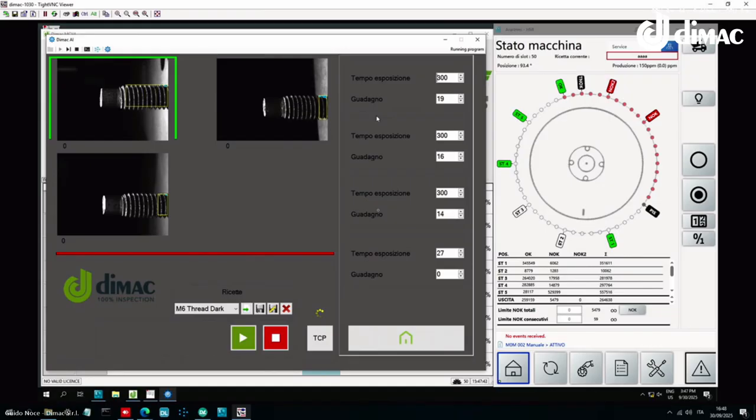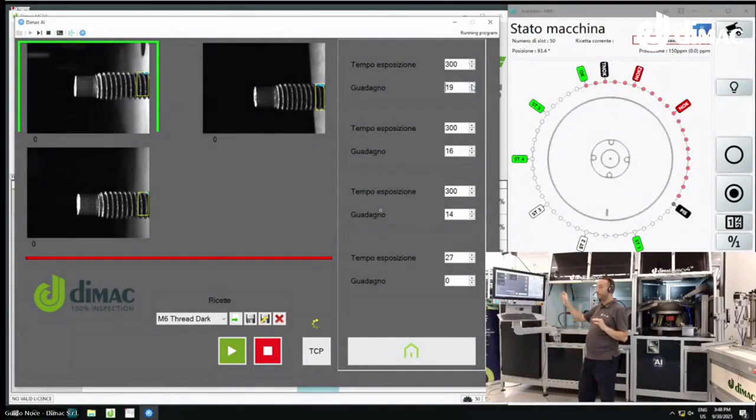So probably by reducing one of these parameters a little bit, we can adjust to accept also these parts that normally should be off. Okay, the height of the parts is also important, but we see a first critical thing. The color of the parts sometimes needs some adjustment, but we can do it with the same training.